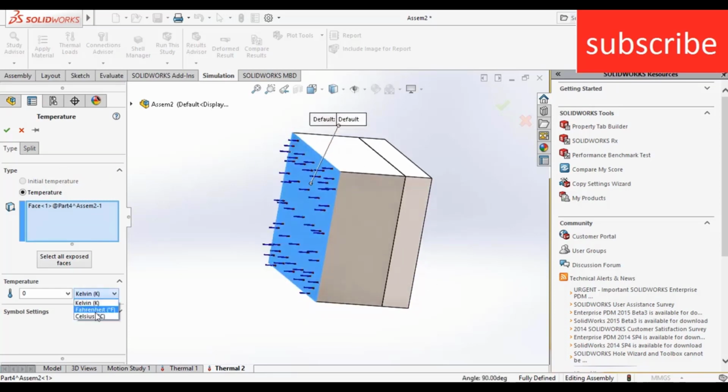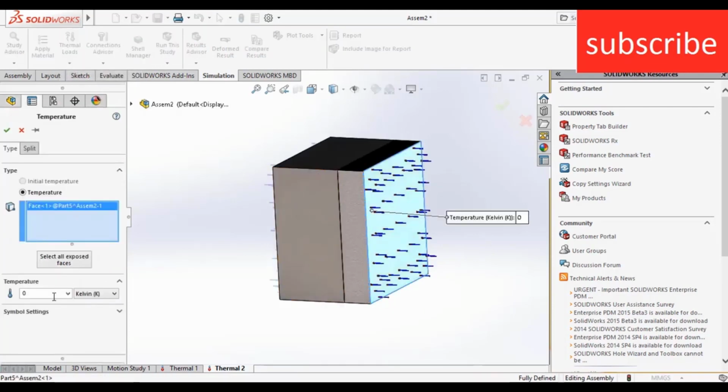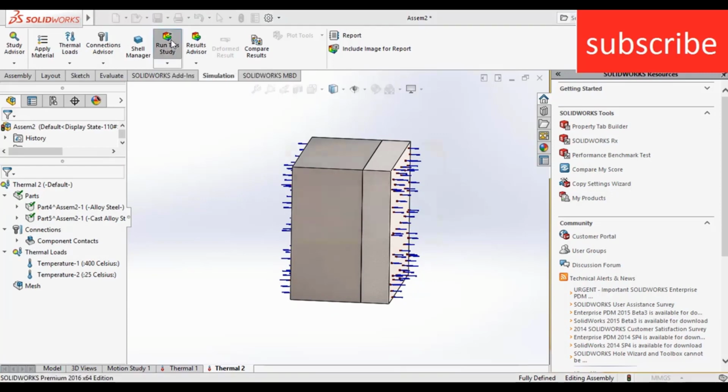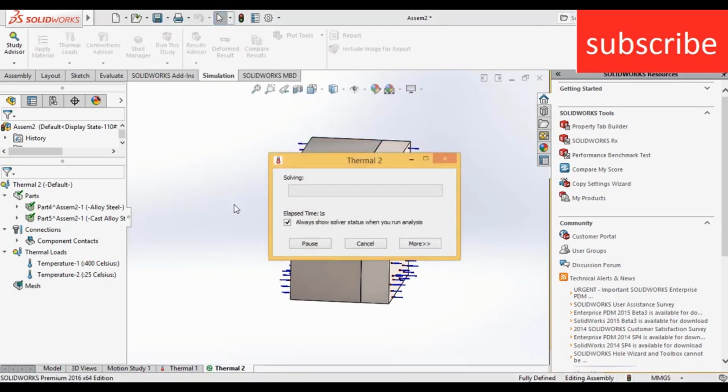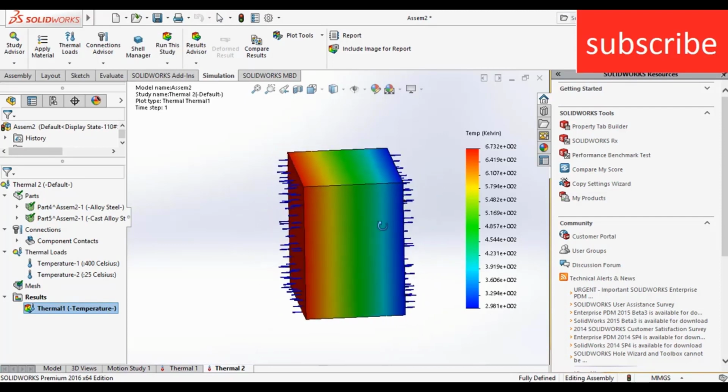Click Celsius, enter the value of Celsius as per your requirement. Again click on thermal loads, click temperature, select this face, select units Celsius, click OK. After that click on run this study, and here we got our graph, our plot.